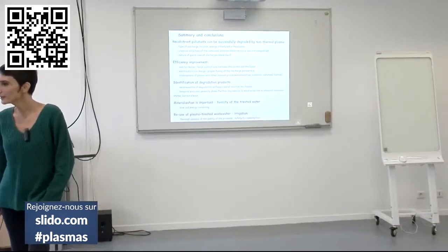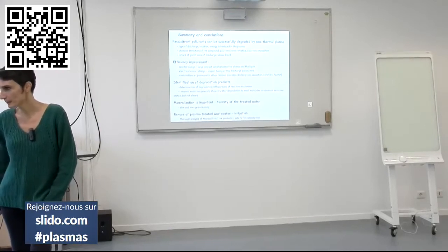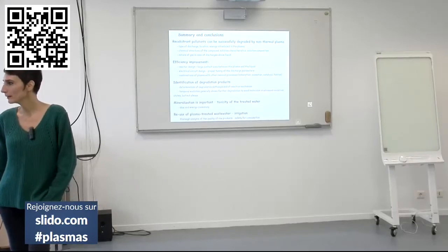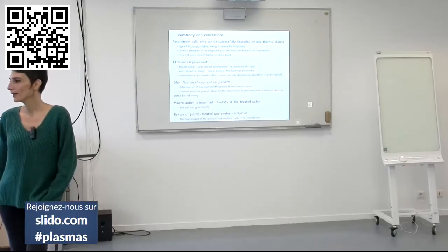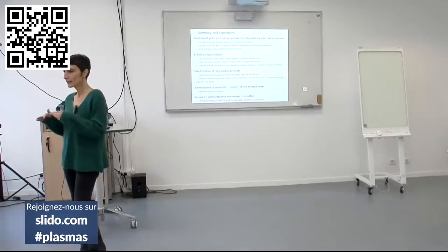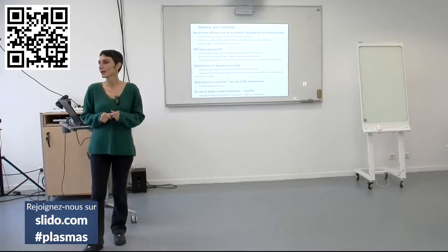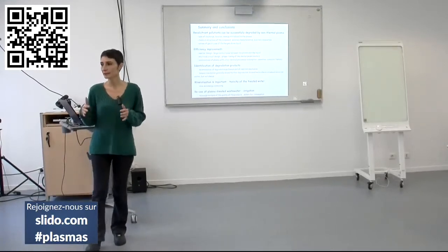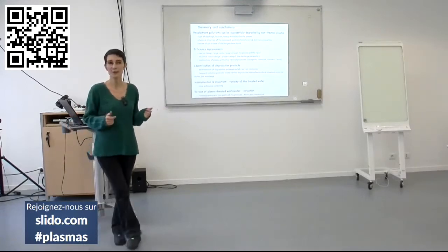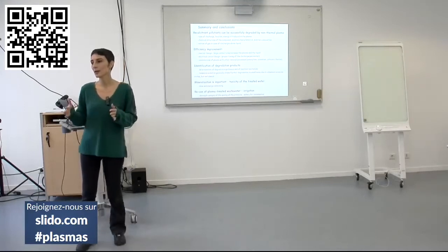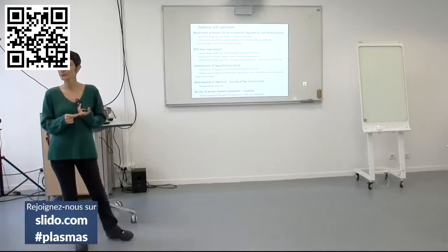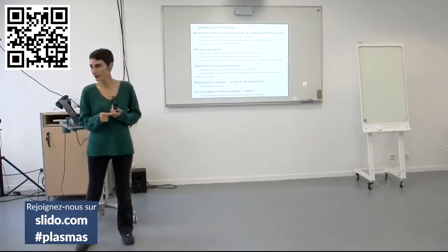Okay, so the first one: for the development of the process, where can we imagine plasma treatment? Pollution sites upstream of treatment plants or at the level of these plants? Okay, so there are several ideas on this issue. The best is to treat the pollutants at the source. So if we're talking of pharmaceuticals, for instance, it would be good to treat the wastewater from the hospitals, or the wastewater from the pharmaceutical manufacturing, because there we have a relatively low volume and we have large concentrations, and plasma has a chance to really do something. So it will be definitely upstream of the treatment plants, at the pollution site.